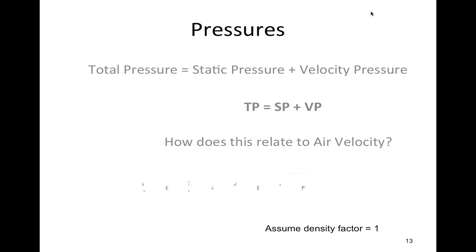We divide by 0.8. We're going to see a table that helps us with that in a few moments. And if you don't know the correction factor, but you do know the density, you can use the second formula to calculate it from the density. This may come up because we might give you a problem where you would use it. Now you have two formulas. If you're given the density, you can use one. If you're given the density correction factor, you can use the other. Again, total pressure, static pressure versus velocity pressure: velocity pressure is equal to total pressure minus the static pressure. Use it any way you want.